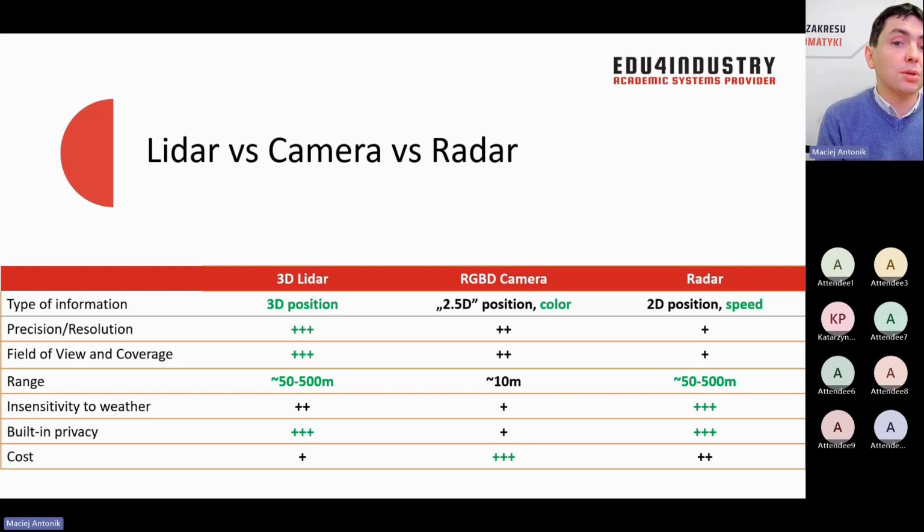On the other hand, if you're using LiDAR, when you only get a point cloud, the point cloud is not enough to get the facial characteristics of a person. You can measure maybe the height of the person, see the general shape of the body, see how the person moves, but you won't be able to recognize that person later. And this is done in hardware, because this is how LiDAR works. It's not software anonymization. So LiDARs are very popular for applications that monitor people because of this built-in privacy feature.